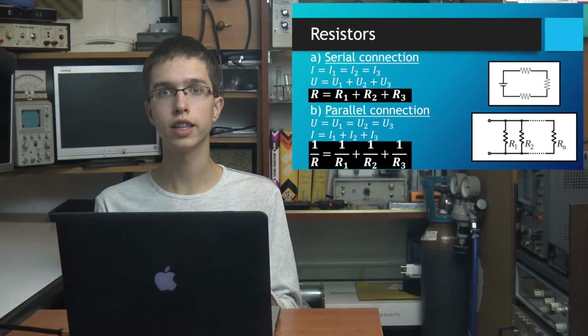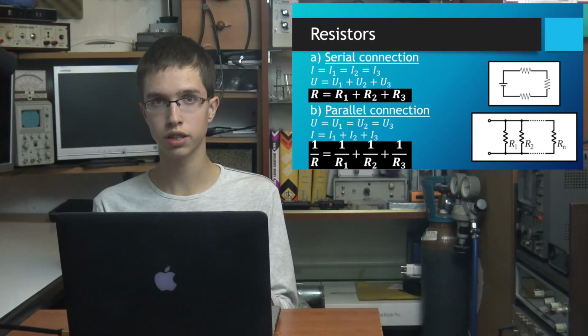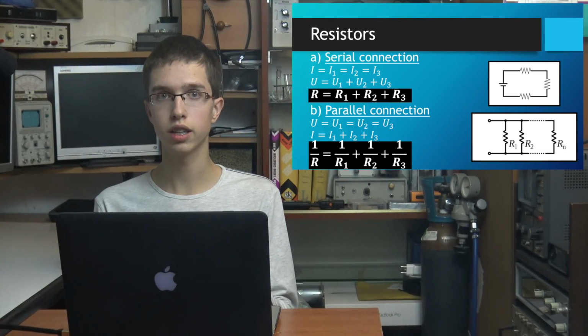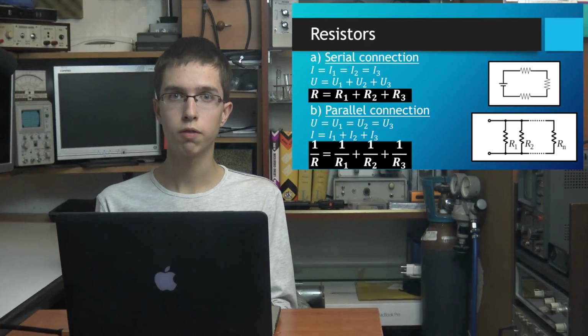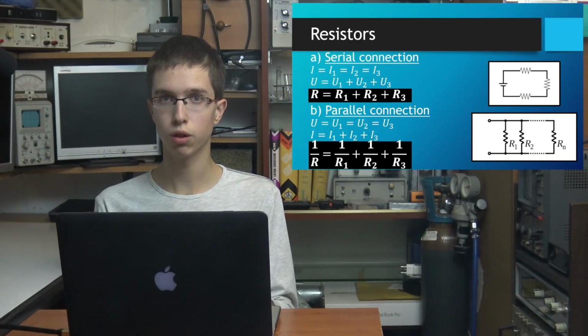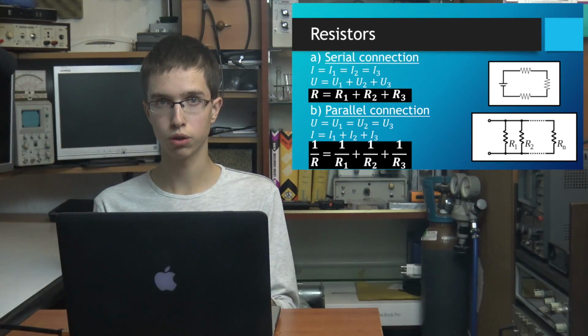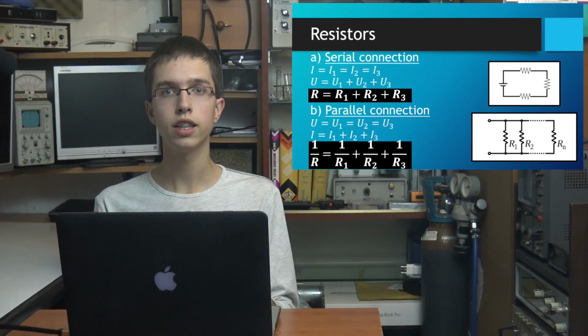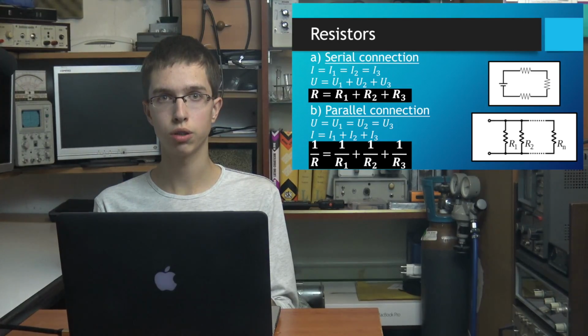From this, we can set equations using the example of the circuit of 3 resistors connected in series presented on the scheme above. First, the sum of all voltage drops, U1, U2 and U3, equals the total voltage U, which is actually the source's electromotive force. And it is gotten by using the law of energy conservation.